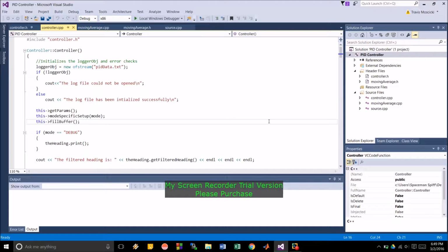But that being said, the P has a really fast rise time, but a lot of overshoot. So if you don't care about overshoot and you just want to get there as fast as possible, a P could do the trick. The PID has a really low overshoot, so maybe you have very strict margins where you can't operate at a higher level than your input.